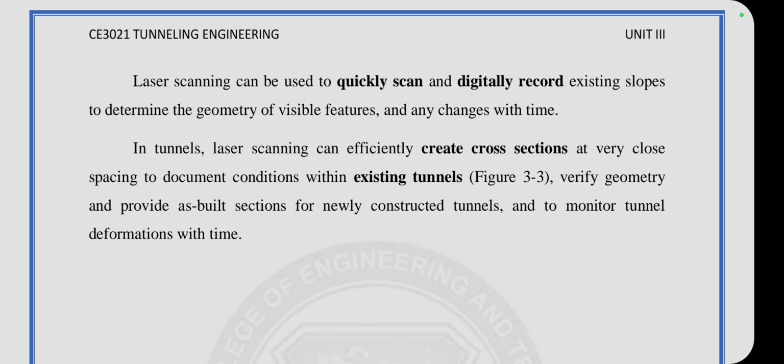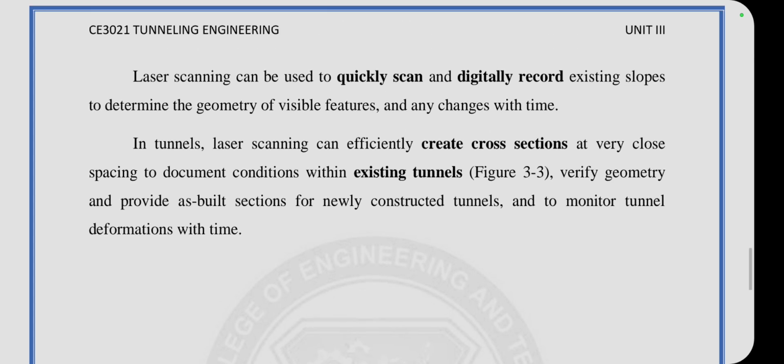So in tunnels, laser scanning can effectively create cross sections at very close spacing to document existing tunnels, verify geometry, provide sample sections for newly constructed tunnels, and monitor tunnel deformations with time.